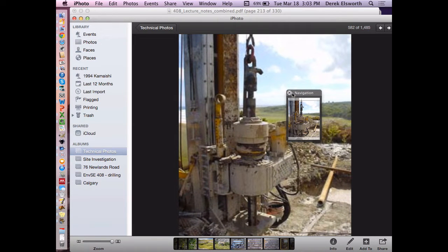So, drill rigs. This is a turntable. This is the drill steel going into the ground with a connection on it to be able to pump water down the drill string. This whole thing turns around, and as it spins, it slowly moves this head down to push it into the ground to actually make it abrade more.